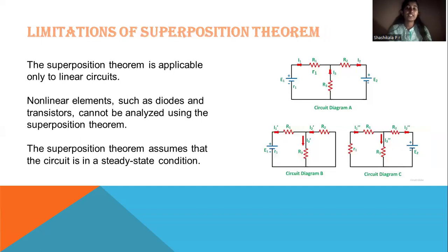Now, let us see the limitations of superposition theorem, that is, what are the drawbacks of superposition theorem. Firstly, it is applicable only to linear circuits. Nonlinear elements such as diodes and transistors cannot be analyzed using the superposition theorem. It is only applicable for linear circuits.